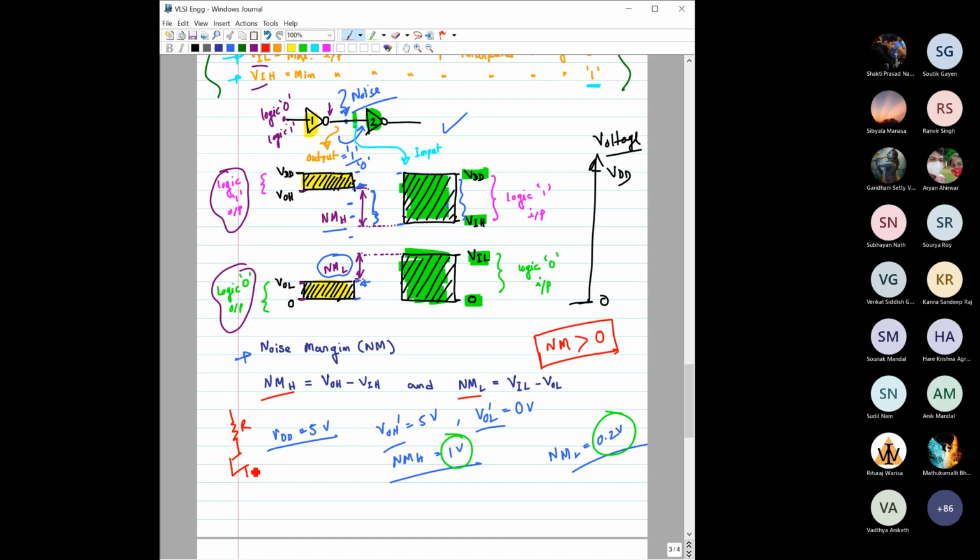Suppose, let us focus again on this NMOS inverter only. You can change the value of this R value, and here this W by L ratio. By changing these two, you can modulate these two values. So you have to make an adjustment, because this is probably not a good design. So let me change these two values and try to make these two as close as possible, means try to make them large and at the same time as close as possible. That is a good design.